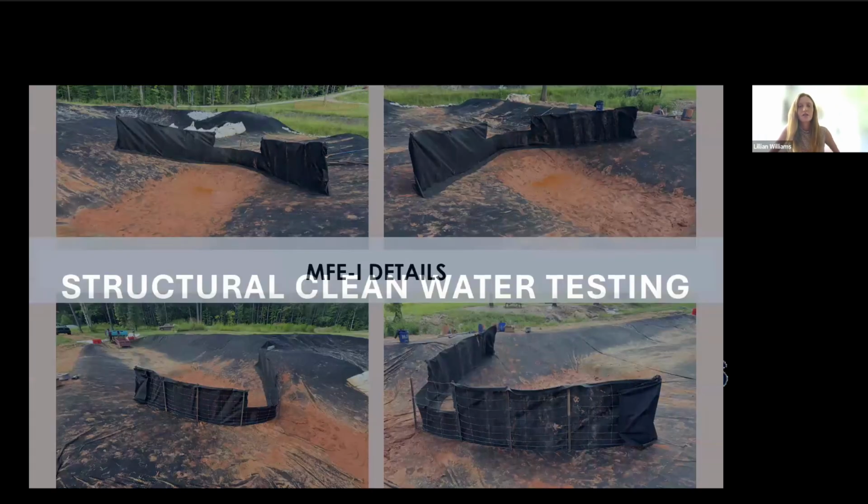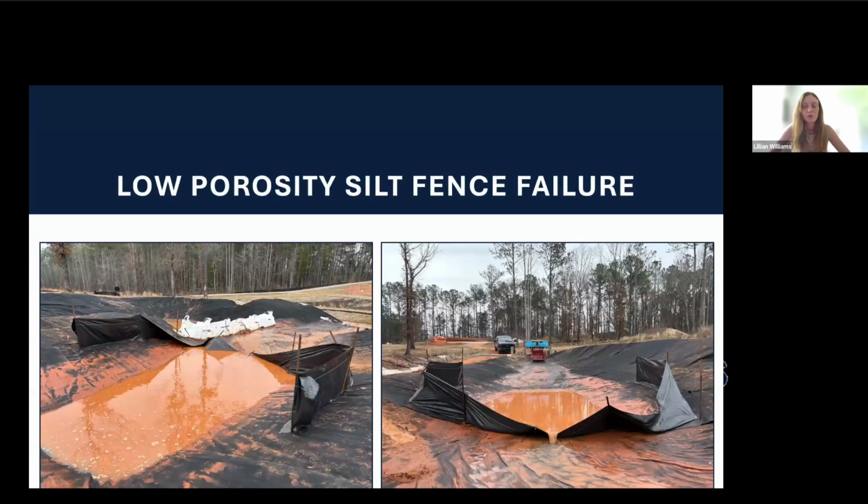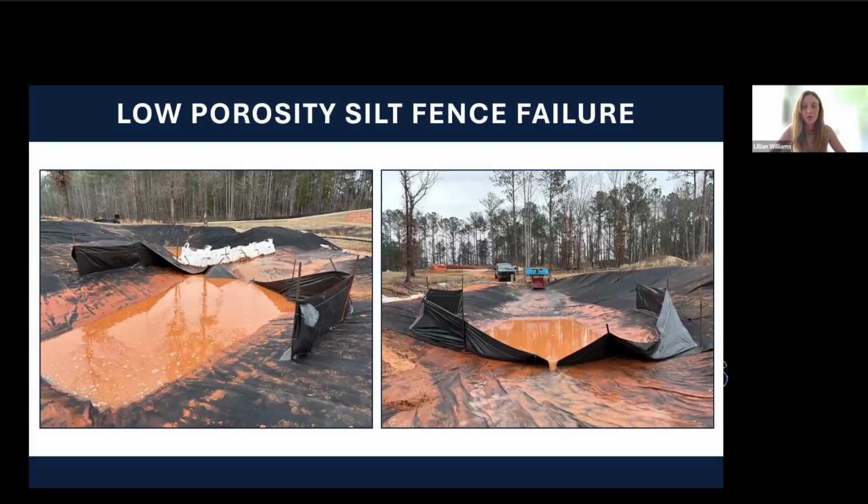So now we get into this structural clean water testing. And that is because of our low porosity silt fence failure. Because we observed this failure, this force that pushed over the fence and the posts, we determined that there was a need to make this structurally stronger.